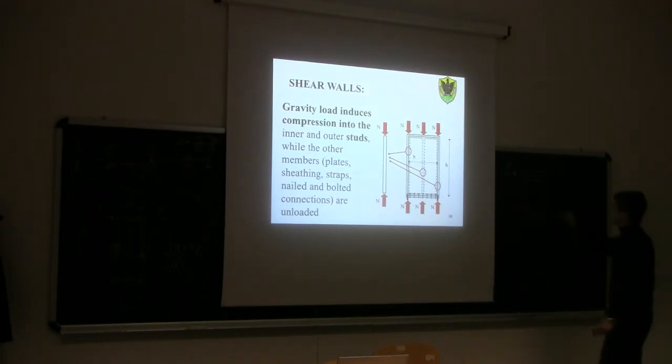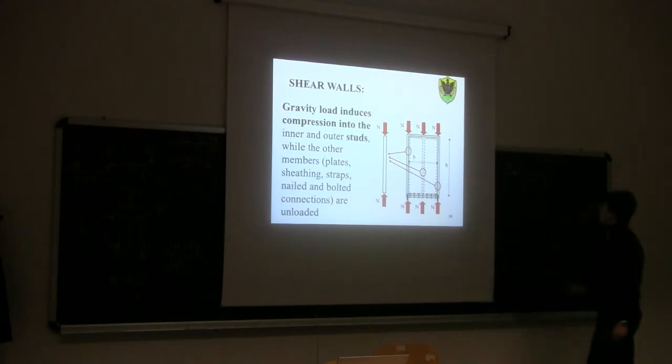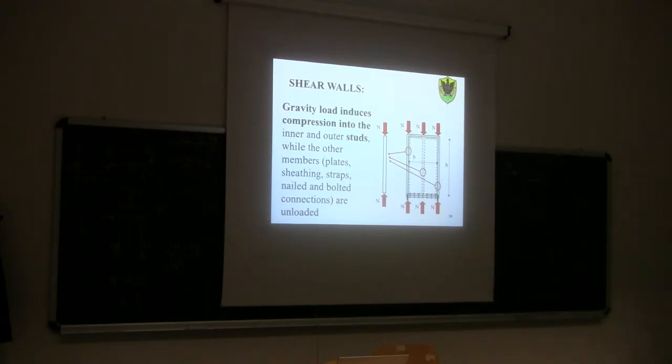Now let's start from the equilibrium. Equilibrium of the horizontal forces of the top plate. So who is going to prevent, due to the force F, this plate from moving in this direction? Who is going to prevent this movement? Who is going to restrain the plate there? The shear panel. Actually, not really the shear panel. Strictly speaking, who is preventing it?